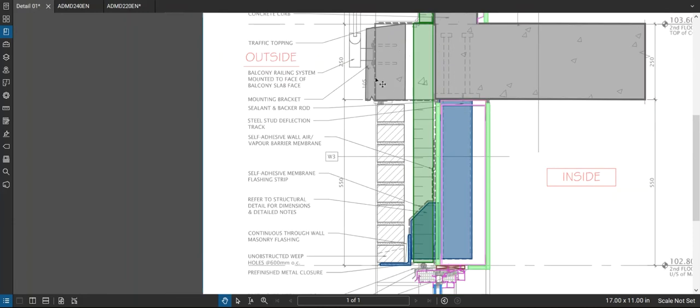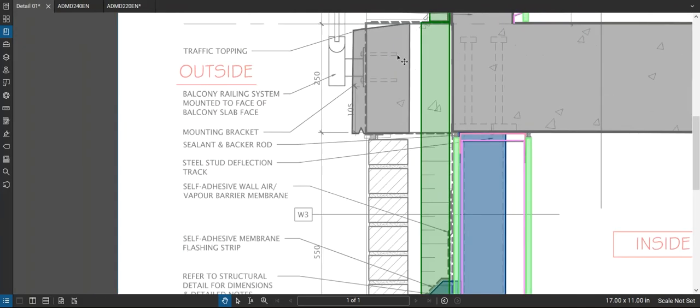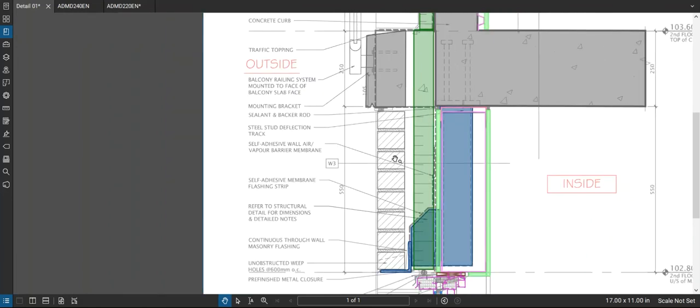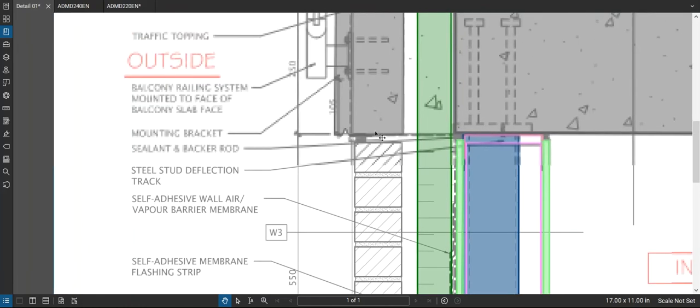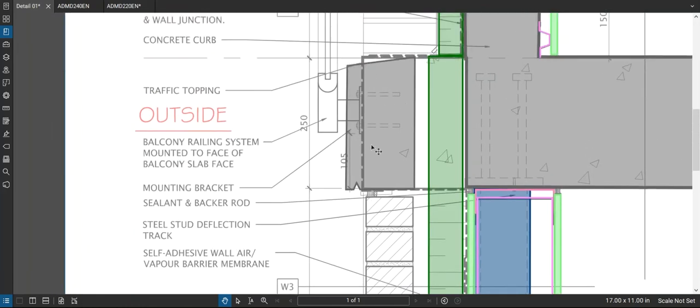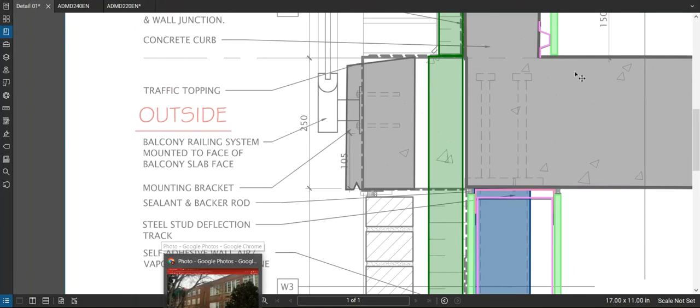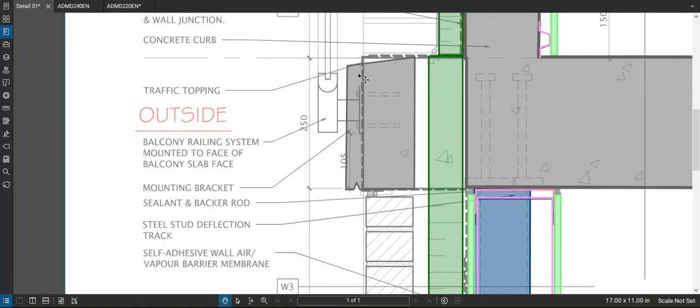Okay, and so for your brick veneer systems, and again, this precast concrete's just replacing the brick essentially, so it's part of that brick rain screen system. So usually you put vent holes at the top of brick and then weep holes at the bottom. They've shown the weep holes here, it looks like. In this case here, you could put the vent holes in the precast panel joints, like between the precast panels just near the top, but probably what I would do is just put them in the brick right here, and that would suffice, I would think, in this case.